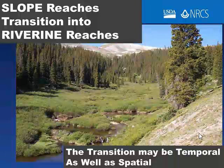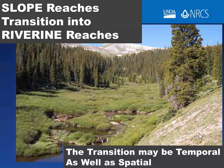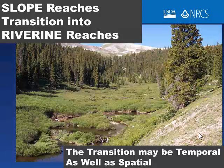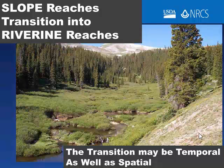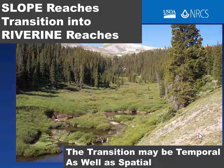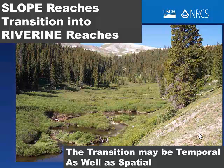Here is a slope wetland in the upper reaches of the watershed near the Continental Divide in Colorado. This is an especially interesting case because we've got a system that's maintained as a slope wetland by the actions of the North American beaver. And the beaver are maintaining a high groundwater table with a series of beaver ponds. We see spring flow flowing out of this system. The wetland boundary is clearly delineated here by the margin of the Engelmann spruce and the shrub willow.